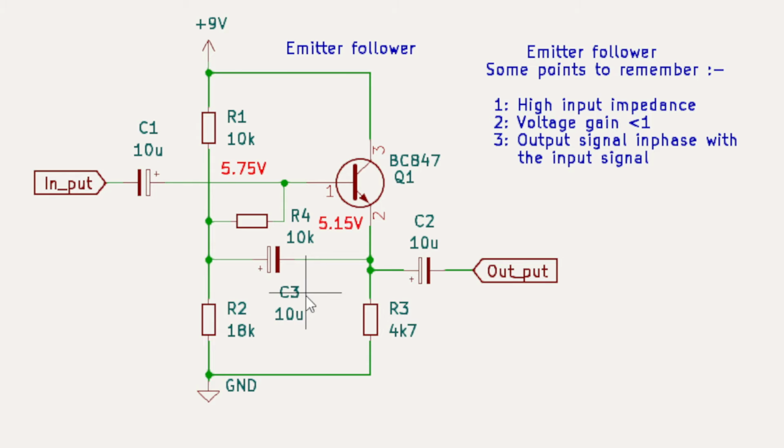Well, as we saw with the other design, and we were increasing the gain, we aim to make the AC signal on one side of the resistor exactly the same as the other. So effectively the signal here is the same as the signal there. So if we feed that back with a DC block to this side of the 10k resistor, we're now going to have exactly the same signal here as we are there. And like before, if we adjusted the gain to give us a 1 volt sine wave here, then we'd also have slightly less than a 1 volt sine wave here, and we'd have a 1 volt sine wave here.